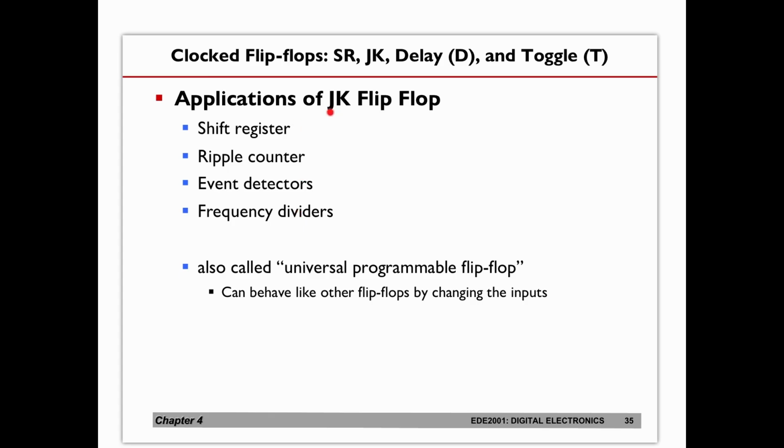Right now, JK flip-flops are what we call universal programmable flip-flops. I'm going to show you in a short while what this JK flip-flop is and how it works. Before that, I will first have to go back to explaining what a JK latch is all about. Previously, we have only done the SR latch, then the D latch. We have not gone to any other latches. So we are introducing something called the JK latch, and with this JK latch you will be able to solve the problem of the invalid state.